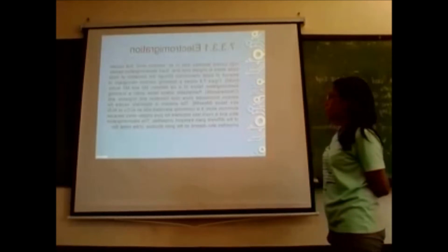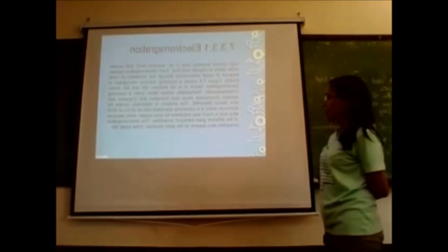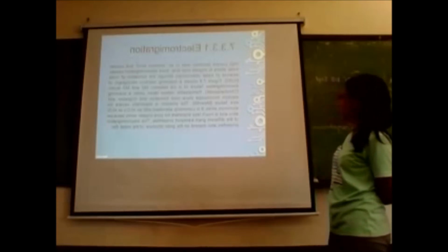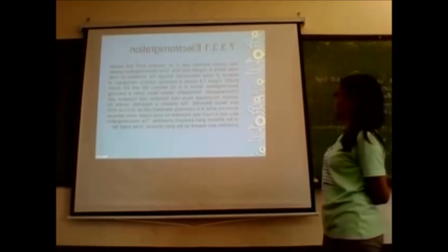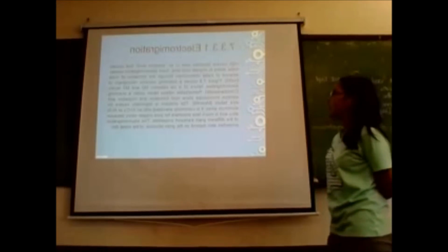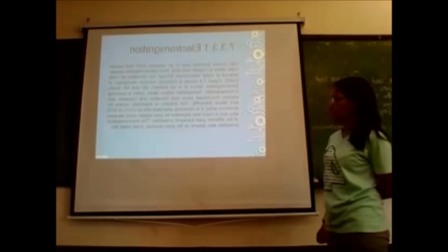The problem is especially severe for aluminum wires. It is commonly alleviated with aluminum-copper or aluminum-silicon alloy. It is much less important for pure copper wires because of the different grain transfer properties. The electromigration properties also depend on the grain structure of the material.